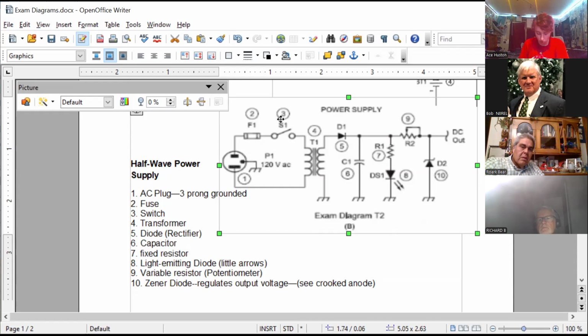It's set up with 2 poles, so whether you're at the top or the bottom, you can turn the light on or off. That would be a double throw. And they have more complicated switches that control three or four different circuits. So this is the basic single pole, single throw.